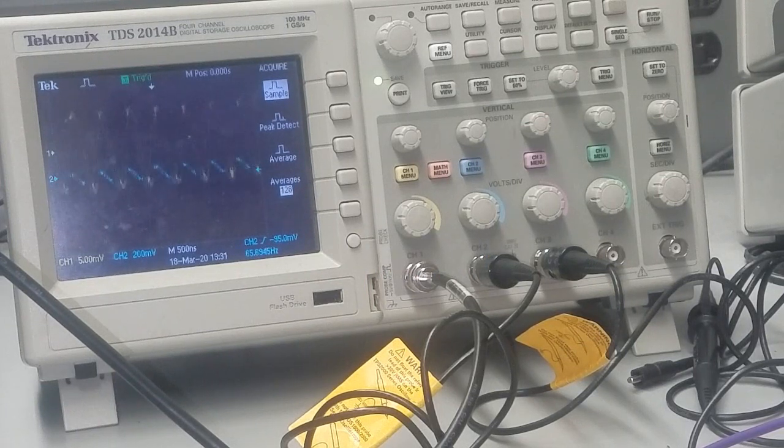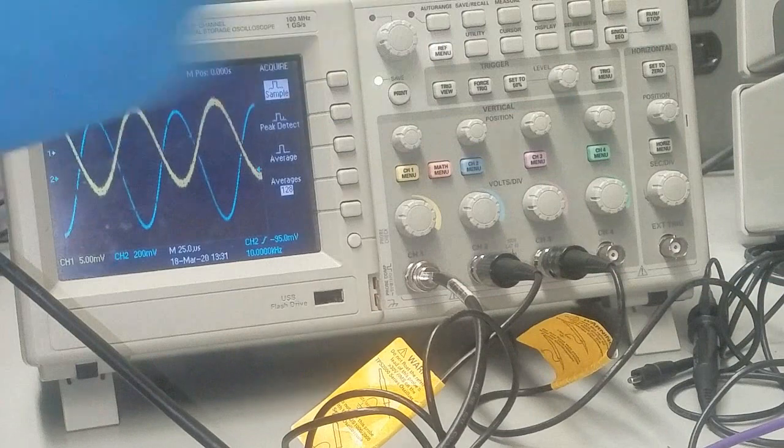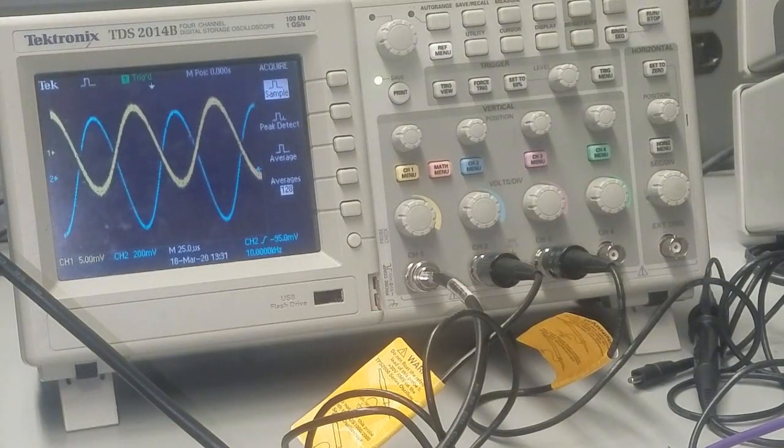So in step number 8, you basically wanted to investigate the clipping of the signal. So what we're going to do is go back to 10 kilohertz. So I'm going to click 10 kilohertz here, and now I'm going to come to the time. I want to show some time here, and we're going to increase the input voltage until it starts clipping.